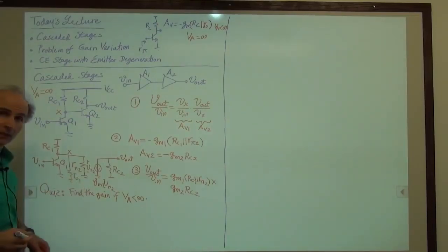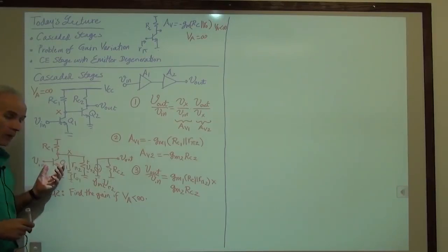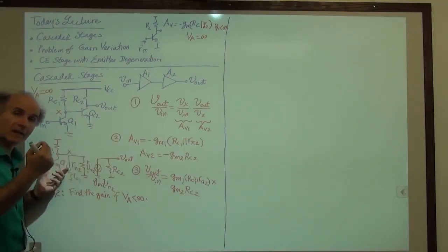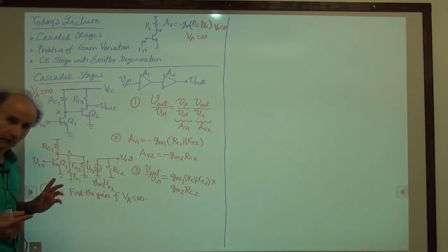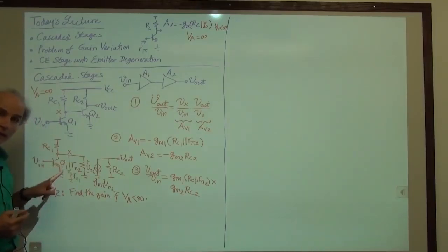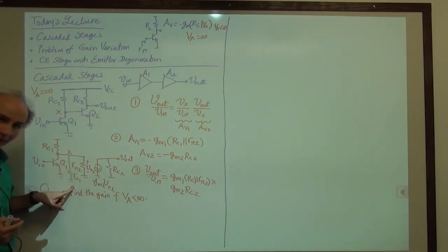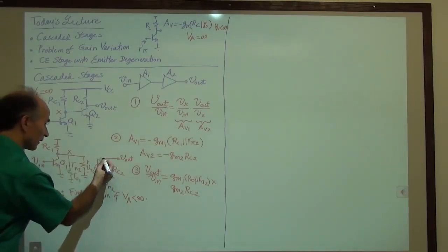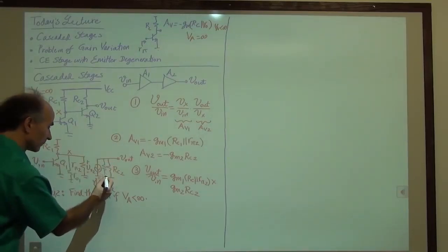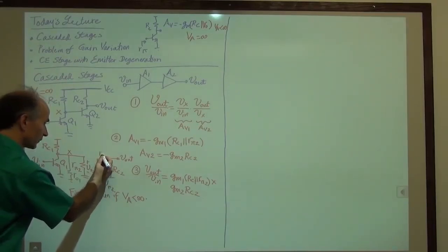And by that, I mean I have a small signal model for Q1. And what I did is I took RO1 out of it and explicitly drew it here. That should not be confusing. So now what's inside Q1 does not have RO1 anymore. We just drew it outside. And for this guy, we draw RO2 here. I'm calling it RO2.